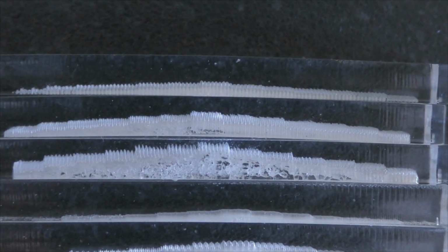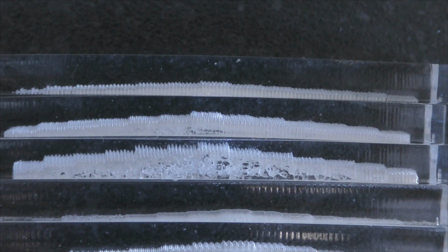Okay, now before we rush off inside and measure these, what we've got on this picture is 3 of my speed runs from the China Blue machine. The bottom one is down at 25 millimeters a second, 50 millimeters a second in the middle, and 100 millimeters a second at the top. Now, obviously, slower means a deeper cut for the same amount of power. But what I really want you just to see is the basic success of my calibration. In other words, you can see that the steps, the power steps, are pretty even all the way across.